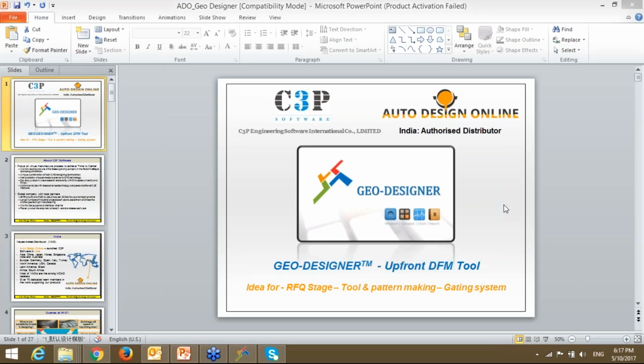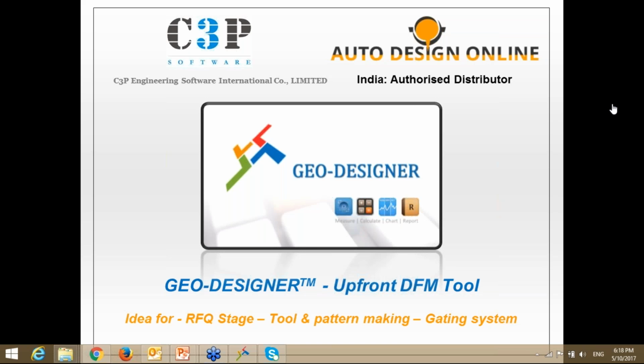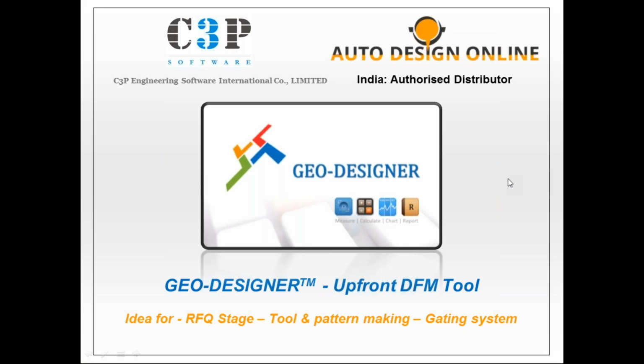Okay, so today will be the first session of our webinar. The topic of today's webinar will be how an upfront design for manufacturing tool could be used by the foundryman or by the OEM to understand, in the shortest possible time, the casting part geometry and where we have the higher masses which are likely to get hotspot or shrinkage later on.